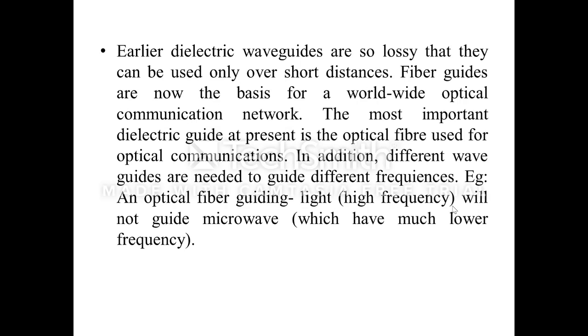Earlier, dielectric waveguides were so lossy that they could be used only over shorter distances. Fiber guides are now the basis for a worldwide optical communication network. The most important dielectric guide at present is the optical fiber used for optical communications. In addition, different waveguides are needed to guide different frequencies. For example, an optical fiber guiding light, which is high frequency, will not guide microwaves, which have much lower frequency.